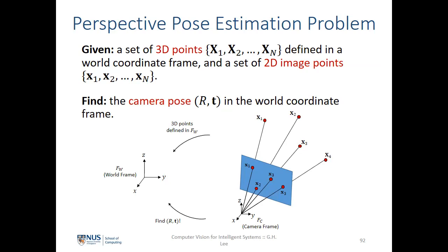The thing is that if you have a drastic change in the appearance, then it becomes difficult. So this comes back to the same problem as place recognition. I mentioned that if I have day and night, place recognition is difficult. This 2D, 3D key point correspondence search is even more difficult. Let's say I have my map built in the daytime. I go out at 3 p.m. in the afternoon to map out the place, do structure from motion, and build these key points with the descriptor. But at night, I go on the same route again, or even with heavy rain, without rain, sunny, cloudy, right? So the 2D key points that I'm extracting here, the SIFT features, might not match because there's appearance change already. That is the key challenge here.